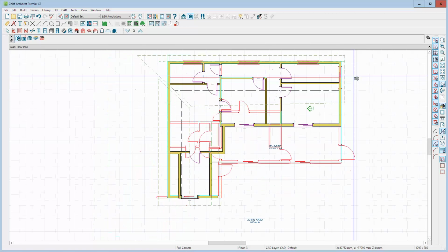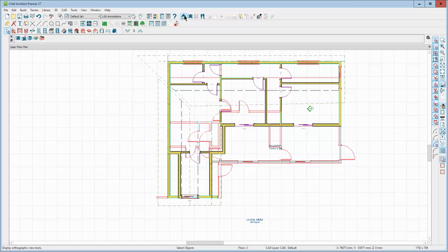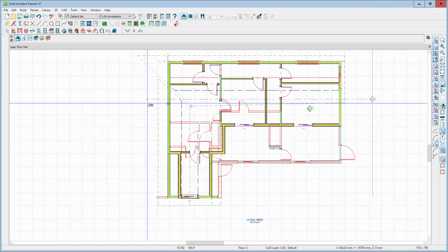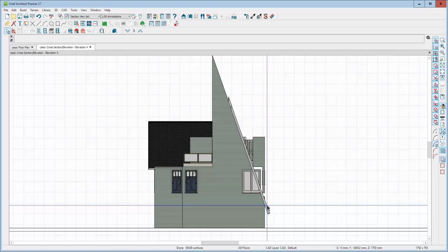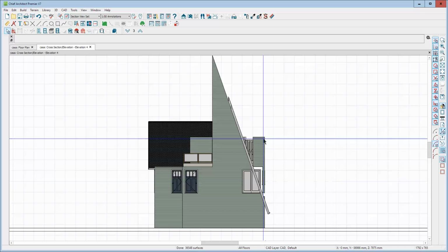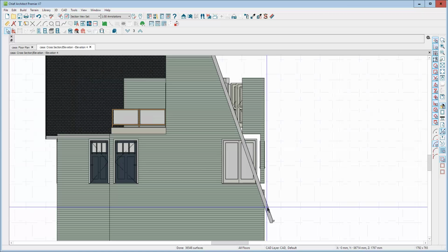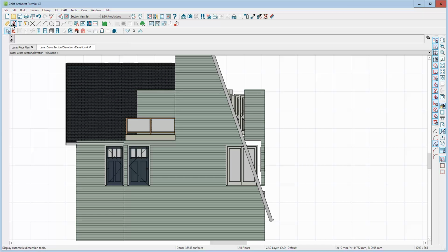The next target would be this roof plane here. I'm going to do an elevation camera on the end of it, and we can see that down here this point right there should probably be up here. So I'm going to measure the difference to where that point is to where I think it should go. Put it right there and measure up to here.